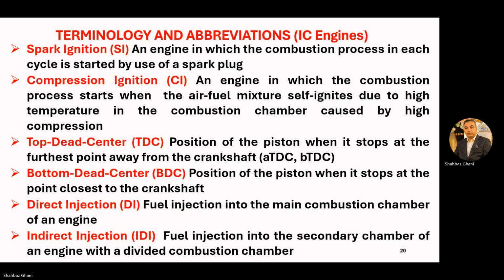Now, indirect injection: the fuel is injected into a secondary chamber of an engine with a divided combustion chamber, meaning you are not injecting the fuel directly into the cylinder or the combustion chamber. Let's suppose you are injecting the fuel at the intake manifold or in the carburetor. That is your indirect injection system.